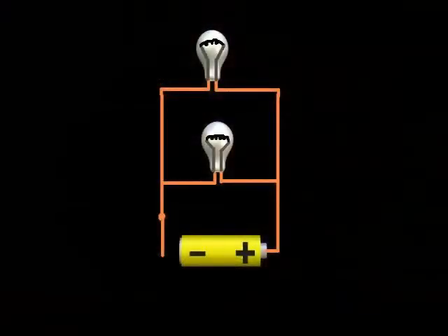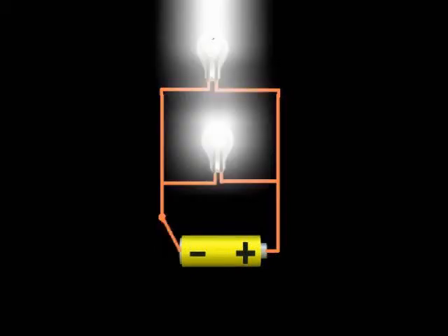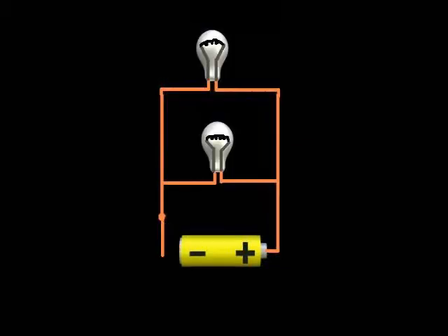Switches are wired in series with the loads they control. In this example, our lights are the loads, and this circuit contains a series and parallel component. The switch is in series with the parallel branches. This is how one switch controls many lights in a room.